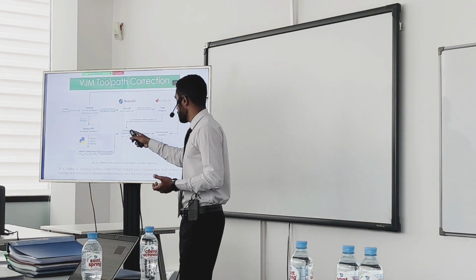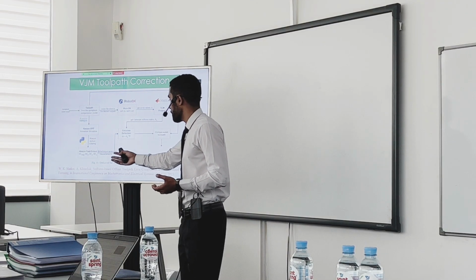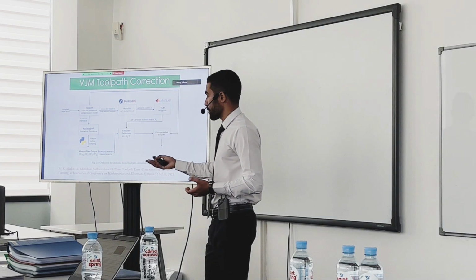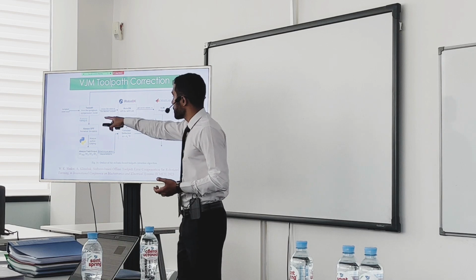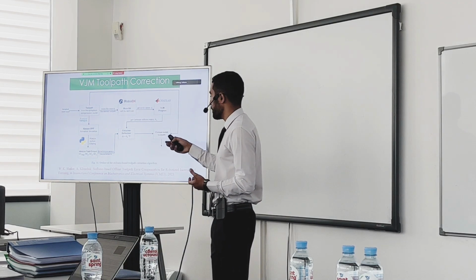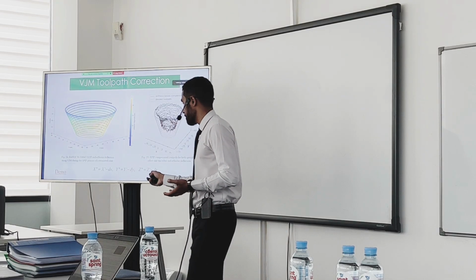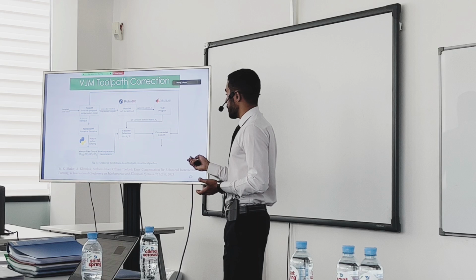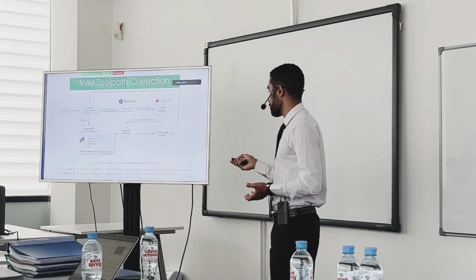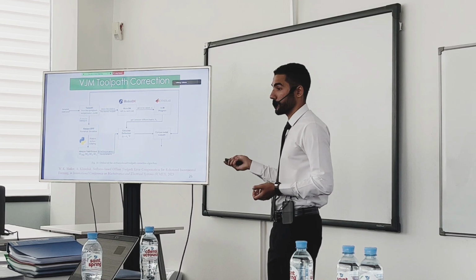So once you arrive at this block, you have the Cartesian stiffness matrix and you have the force and torque sensor measurements, so you can get the deflections. And again, using the desired tool path with this deflection, you can calculate the new compensated tool path using simply this equation here. This work has been accepted for publication in the International Conference on Mechatronics and Electrical Systems, and it will be presented next month.